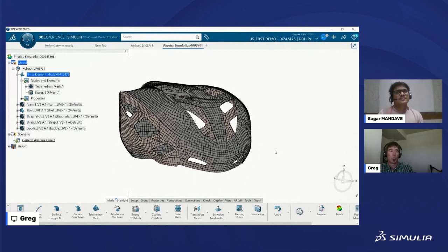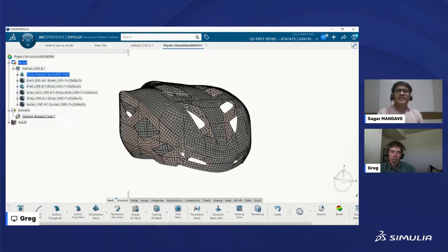And so that gives me really great accuracy with just this basic simple mesh. And I can still model this all as a solid. I don't have to do any mid-surface extraction and figure out what to do with that gap between them and all of that. So it's a really, really nice, neat sort of process. Okay, so there we go. We've got that meshed.